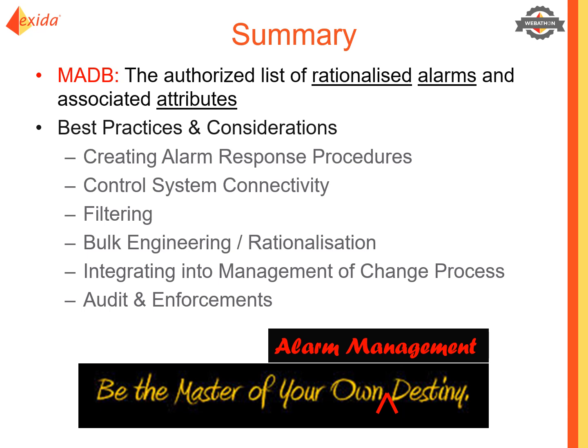We have used the best practices and considerations in creating alarm response procedures. We can use the information that's stored in the master alarm database and connect it straight into our control system. We can use filtering in the SILAlarm tool to bulk engineer and rationalize alarms. We can integrate that information into our management of change process, and we can audit and enforce changes that we've made or have been made to the master alarm database.